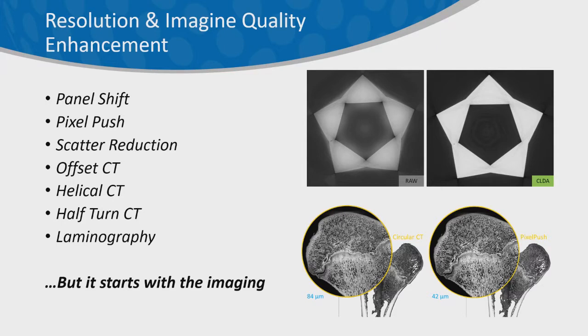And then there are also laminography tools, where we're completely flipping how we capture the data. It's really optimized for getting very, very high resolution on larger circuit boards. But again, we're confined to looking at maybe a smaller window. So there are ways to use laminography, capture very, very small sections of a board at high resolution and stitch those all together.